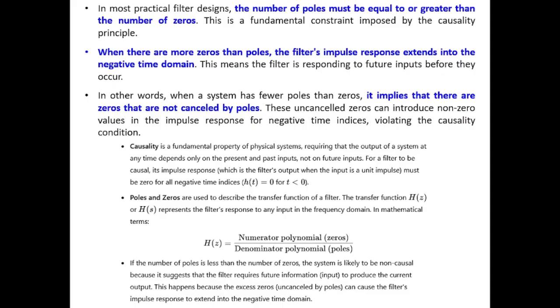And what it does is that this slight mismatch in the poles and the zeros, the zero will pull your amplitude value low. If you consider the y-axis as the amplitude, it will be low, and just beside that you will have a pole which has a very steep rise. So you will get an unwanted spike in your system. Okay, so in the analog domain it is advised not to place a pole and a zero at the same location.